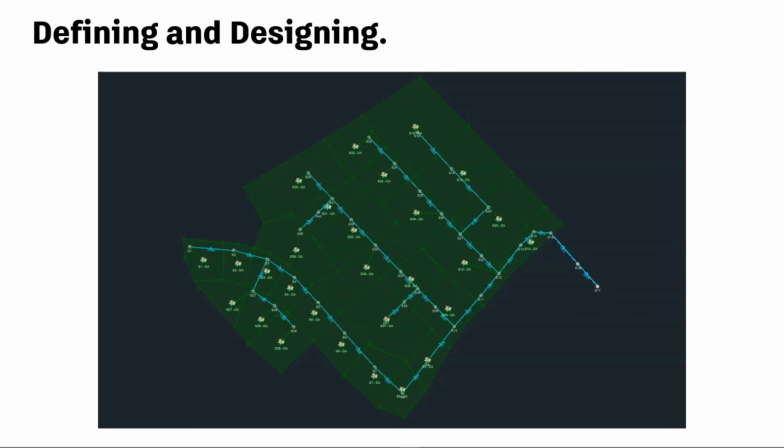Furthermore, specifying the proportion of impermeable surfaces within the catchment area also plays a role in determining the amount of runoff generated, all of which contribute to the peak flow. With all this information defined, it could be at this stage we design the pipes to meet the no surcharge criteria.